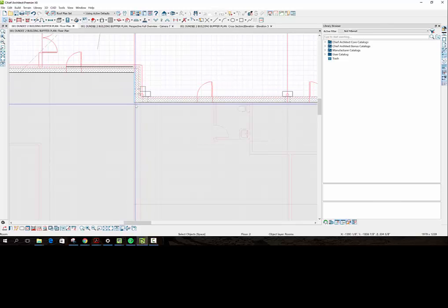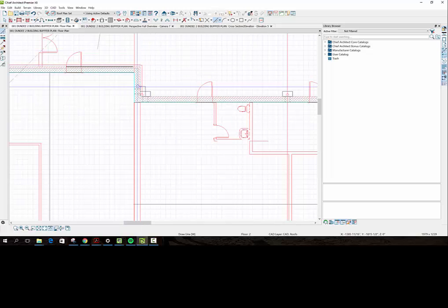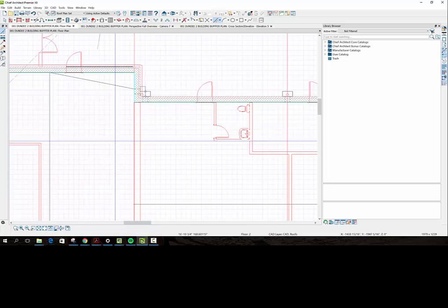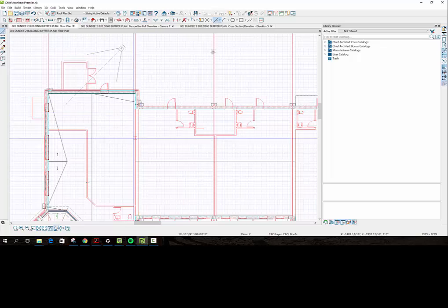The thing I'm not happy about is what happens to this water here. We're going to need a little teeny tiny something here. We got to get that water out of there. So now the water is there, goes there. Control, snap to that line there. All right, now I'm sure we got that draining pretty good. Okay, this is how we do it. This is a low point. And that's the low point.